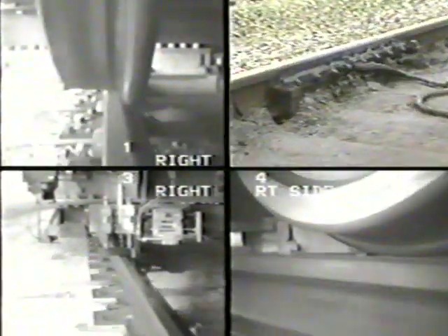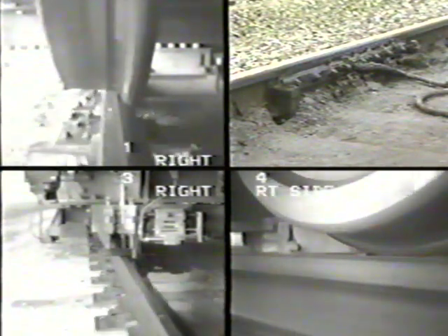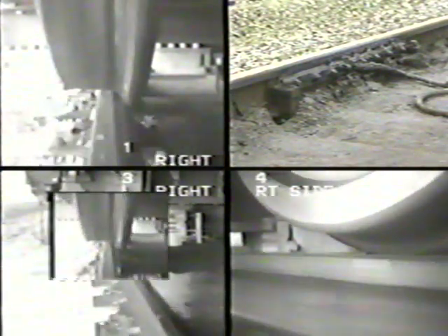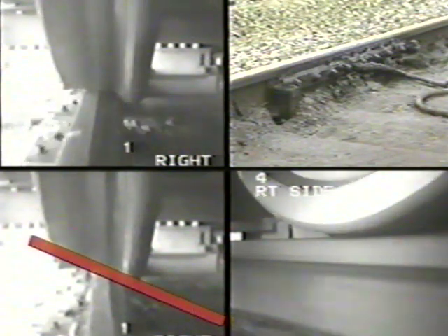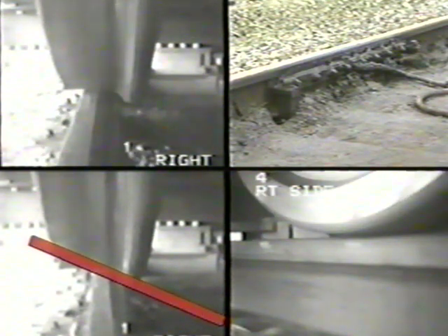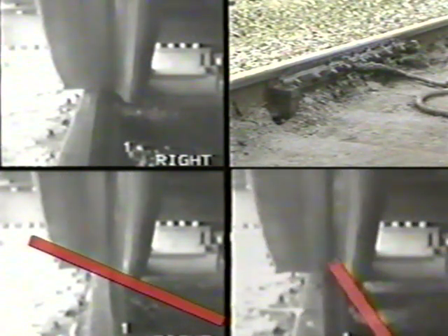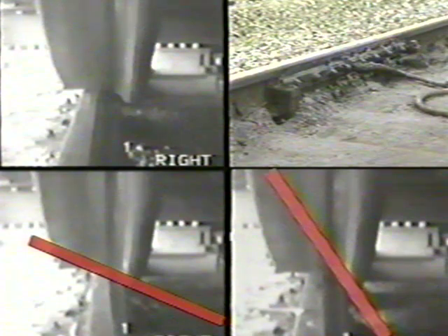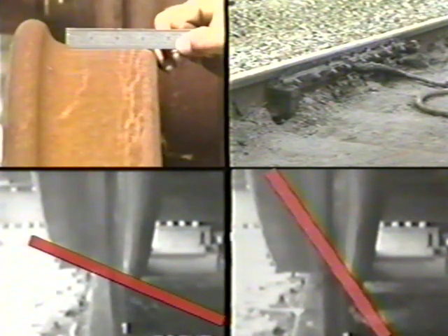A lubricated rail will be more difficult to climb than a dry rail. Also, a shallow contact angle between the wheel flange and the rail will allow the wheel to climb at a lower lateral force than compared to a steep contact angle. The risks of low-speed flange climb derailments can be reduced by lubricating the rails and maintaining acceptable wheel-rail profiles.